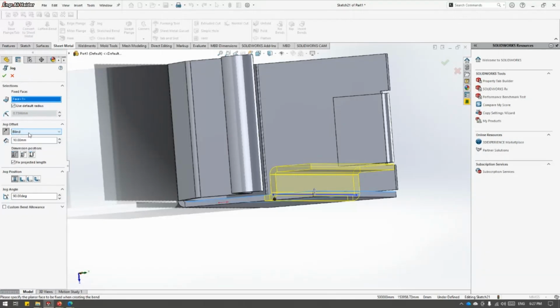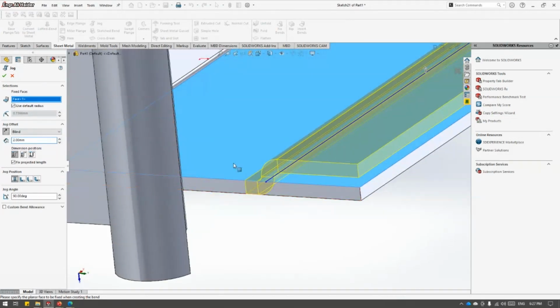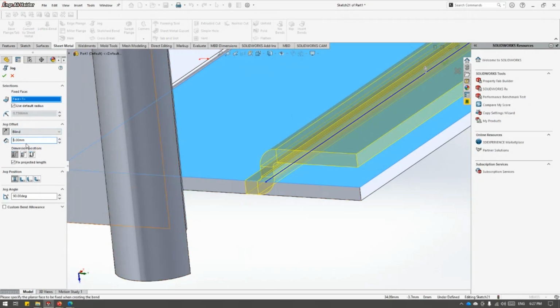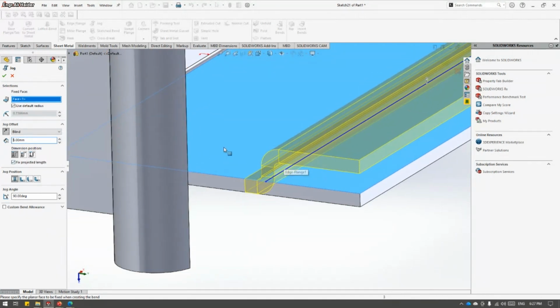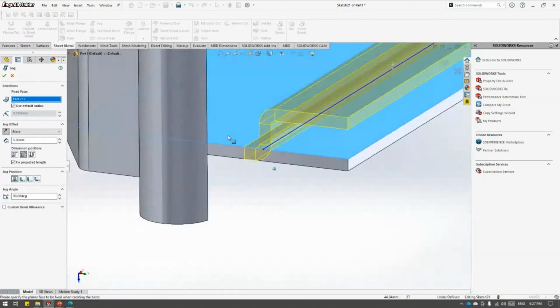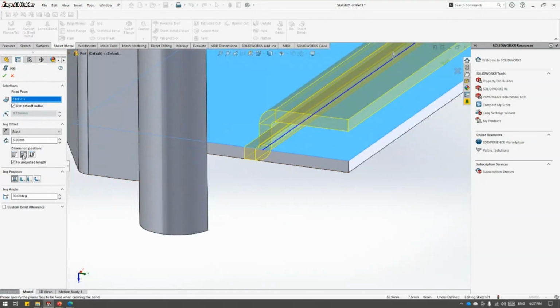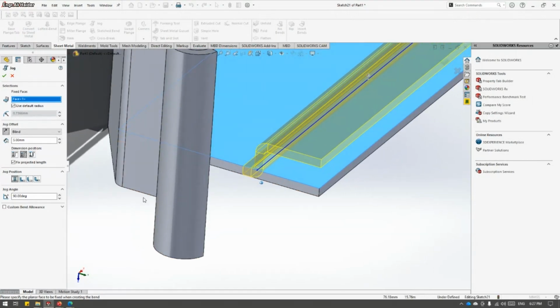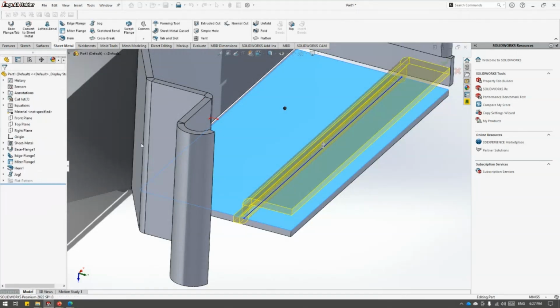We have the jog offset, which means if I change the value, you can see from the face it is offsetting 2 mm in the upward direction. I can change the value, and this is how it changed. And from these icons, you can see how the distance is changing. It's actually like from this face till the top face it's 5 mm. So if I change that, from the bottom of this yellow face and this top face, it's 5 mm. So these icons can help you visualize what you are doing on the screen. So that's how you create jog.